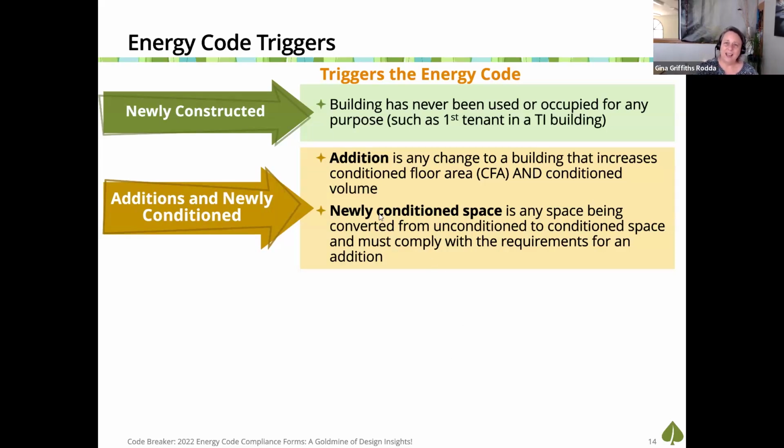An addition means every feature of that addition, the floors, the walls, the windows, everything that's there has to meet current code. It doesn't mean the existing building to remain as is has to meet the energy code, only that addition has to meet the energy code.